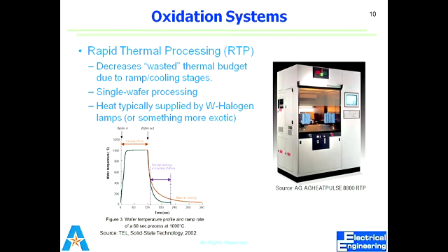temperature. So it means that if I have put one wafer at 1000 degrees centigrade for 1 hour, while the other wafer has been at the same temperature of 1000 degrees in the same furnace for 2 hours, for a greater period of time, the second wafer has got greater thermal budget because it has been exposed to 1000 degrees centigrade for a longer period of time. So the time of exposure to a certain high temperature is actually counting your thermal budget. That tells you what your thermal budget is for this device.